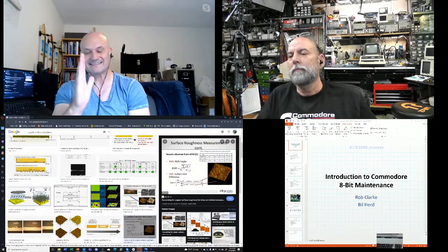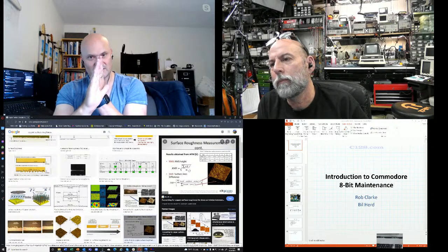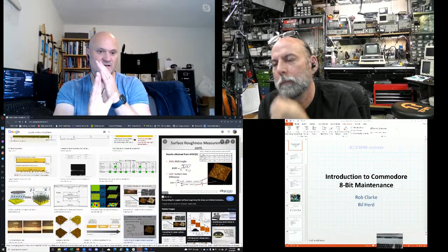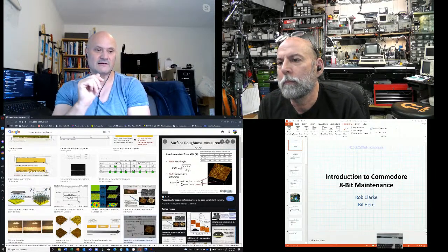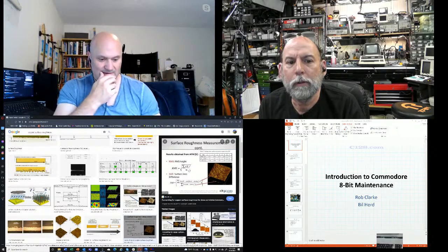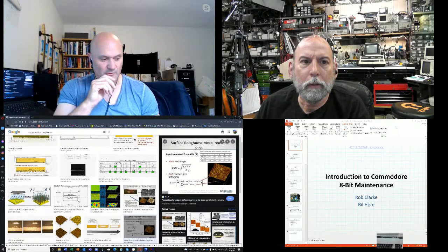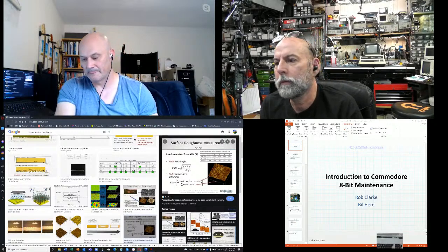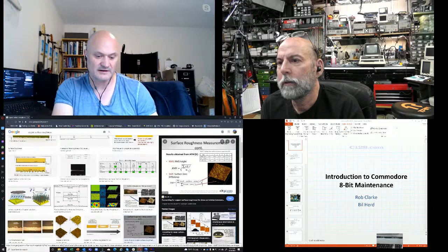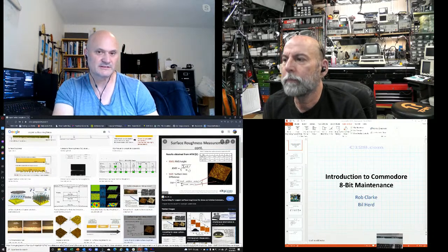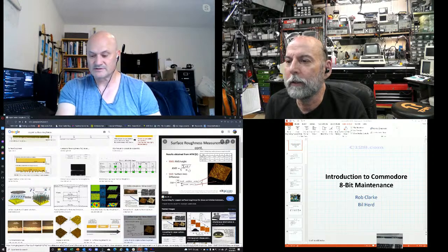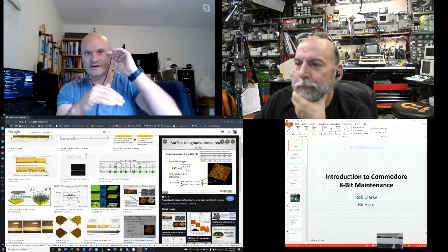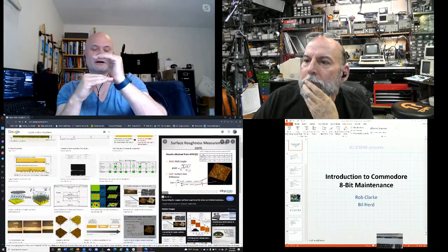And if you need to maintain that edge and keep it clean for whatever reasons, maybe it is a clock edge and you have to have a good sampling for other signals, well, this is where your losses, your impedances, and things like skin effect can really have an impact on high-speed digital designs. Right. So you want a nice open eye diagram where your transitions are clear and you've got a very definite 1 and a very definite 0.